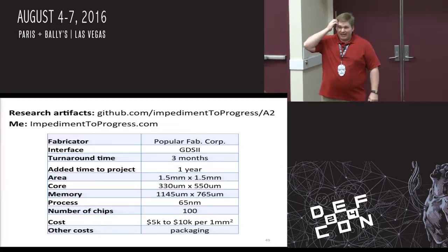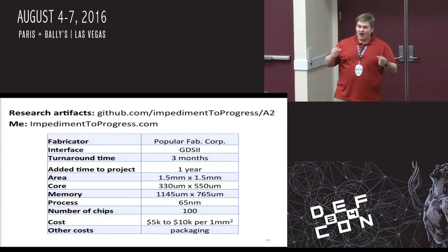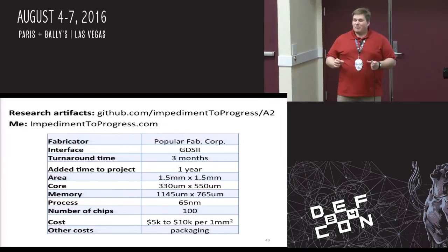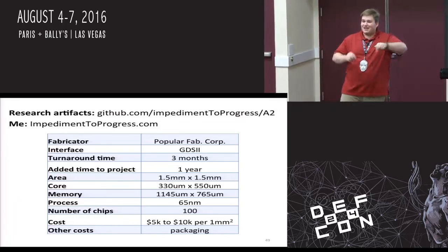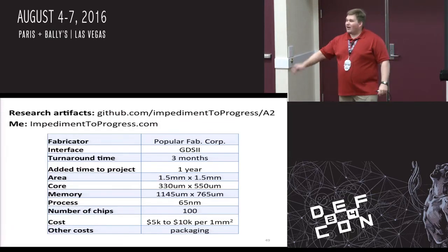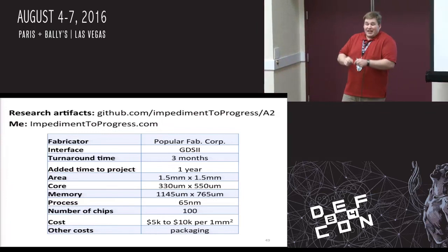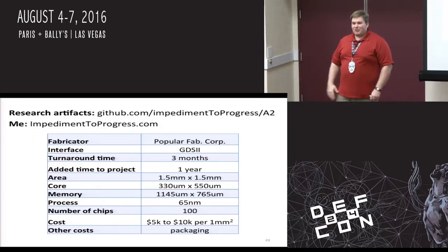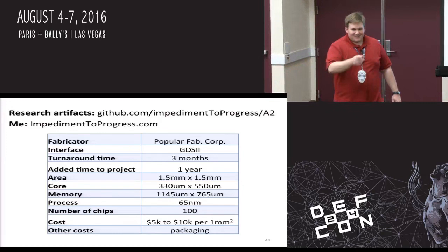So one observation, and I think what you're hinting towards, and I learned about this actually after we even published the paper, is that most manufacturers put spare cells on the hardware itself. I don't know if you knew about that, but right now I could actually say we have a zero modification attack because we don't have to add a cell. That's when you see processor steppings. They take spare cells and recode logic in those spare cells because it saves you the NRE cost of having to do an entire remask and respin. It's very cheap to connect things up after the fact. So they populate the entire thing with spare cells when they ship it because they know they can do a very low level patch. Yes, we could take one of those spare cells and swap it out with our own, and we would probably have an even more stealthy attack. So does that answer your question? Yeah, we thought about it, but I didn't learn about it until afterwards.